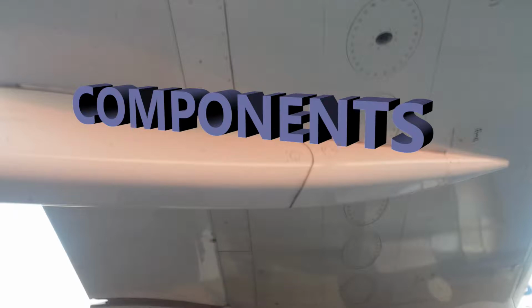So what you've got is 5 wing tank MMIs. Okay, so you've got those magnetic indicators located at the bottom surface of the wing tanks. And the center tank MMI, that one is in the belly fairing. And that's directly below the center tank. All right, for the measurement of that fuel for quantity.